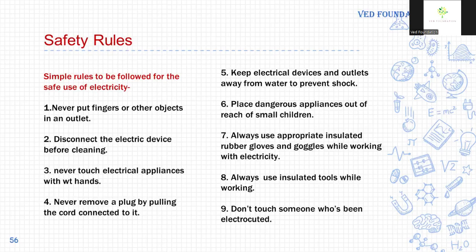Never remove a plug by pulling the cord connected to it. Keep electrical devices and wires away from water to prevent shock. Place dangerous appliances out of reach of small children. Always use appropriate insulated rubber gloves and goggles while working with electricity. Always use insulated tools while working. Don't touch someone who has been electrocuted.